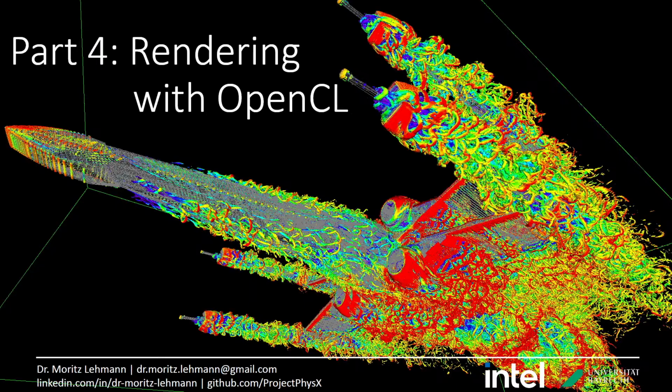That's the thing. Rendering with OpenGL is not supported on some of the data center GPUs, and it is also troublesome with hardware. So what I did instead was write my own rendering engine from the ground up directly in OpenCL. That has the benefit that I can do in situ rendering. I simulate a couple of time steps with Lattice Boltzmann, then pause the simulation, and all of the data is already in the fast video memory. So I can just read out the data from video memory and render it to an image, which is in the end just an integer array, and then send the image to the screen.